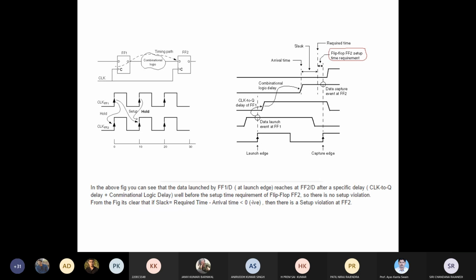Okay. So did you get it? This is one important aspect called slack, which is related to your required time and arrival time. When timing analysis is done by using PrimeTime or similar tools, after each timing calculation for each timing path, they give the slack, positive or negative. It does this automatically. You give the design, constraints, clock, timing constraints, and gate-level input to your PrimeTime tool.